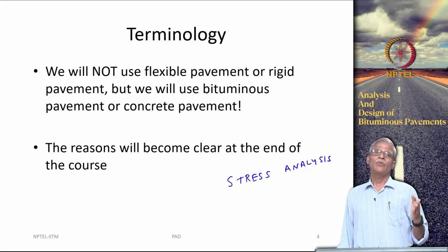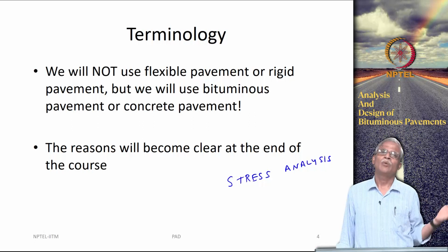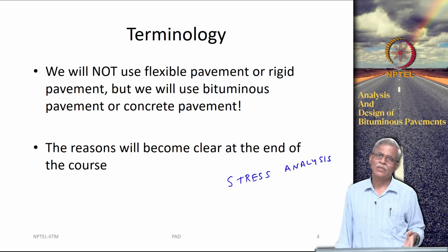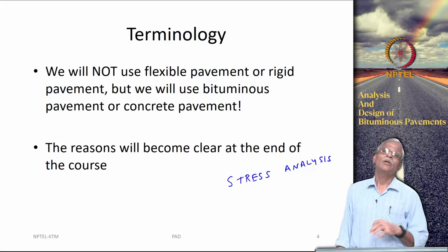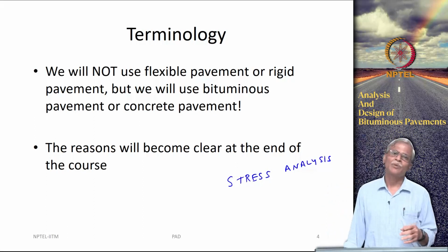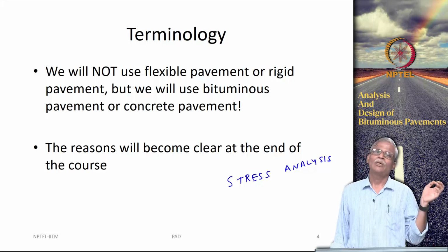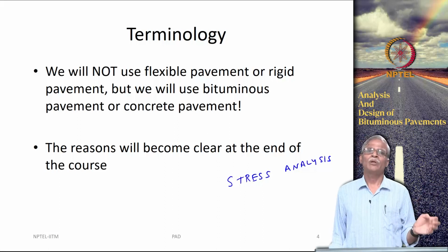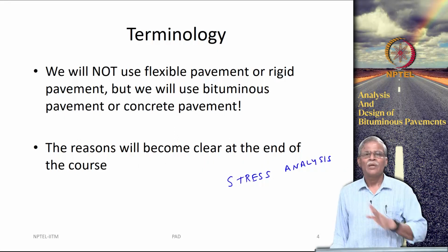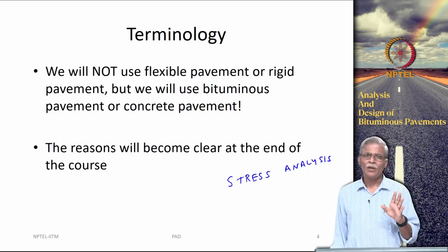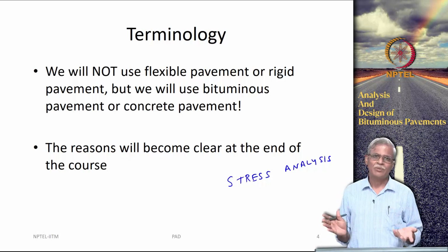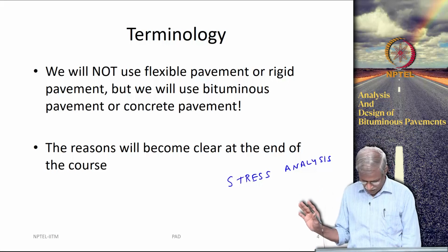For concrete pavement, we use what is called beam on elastic foundation, Winkler model, Pasternak model and all those things. It is possible that you can model concrete pavement using layered elastic theories. It is also possible that you can model bituminous pavement using the Winkler foundation. So, there is nothing flexible or nothing rigid about it, right.